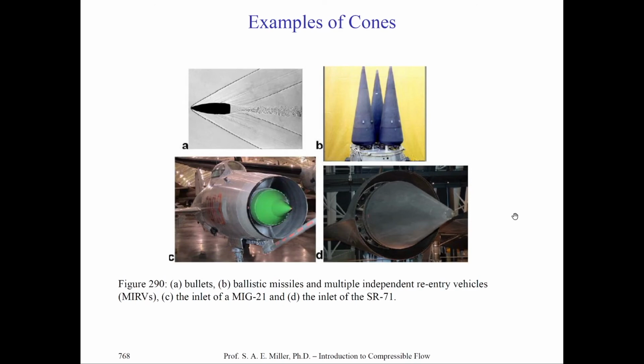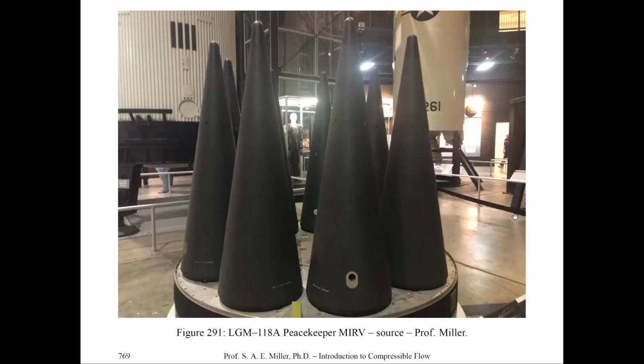So now you can see that really, for these conic cases, you cannot use 2D planar solutions at all. In fact, we do that in the class to illustrate the analytical concepts. In reality, you would of course have to use conic equations for theta-beta-Mach number curves to solve these problems. In reality, today a lot of people simply do computational fluid dynamics to try and capture these flow effects. But of course, CFD is very complicated, and you'll have to spend a lot of time to understand the physics and equations before you can solve them numerically.